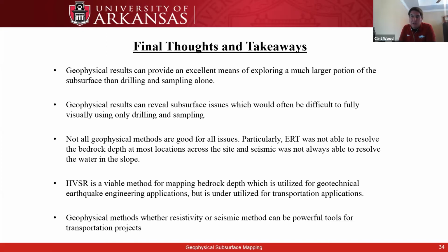So we saw this in this particular project, that you can't just have one tool in your toolbox and be able to do a good job at a lot of sites. That particular ERT was not able to resolve the bedrock depth at most locations across the site, but provided an excellent resolution of where water was in the site, where was it pooling in those particular cases.